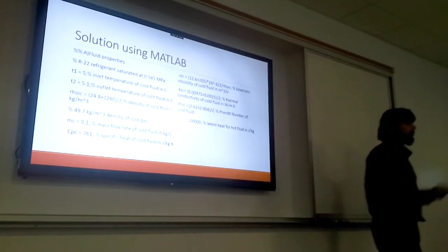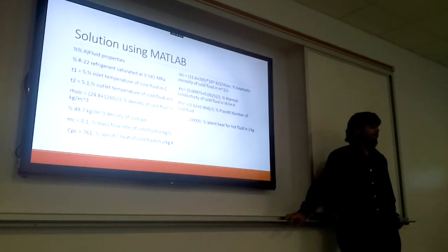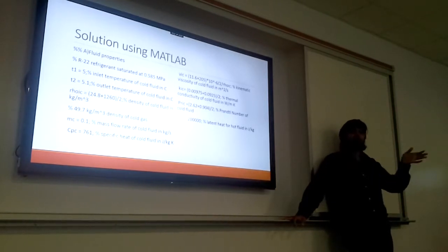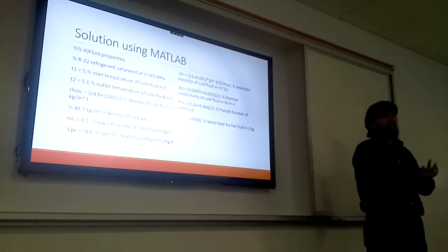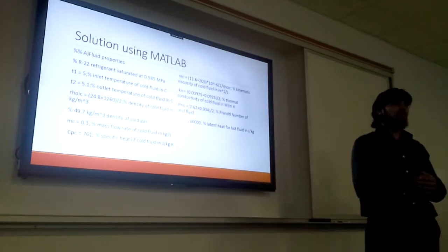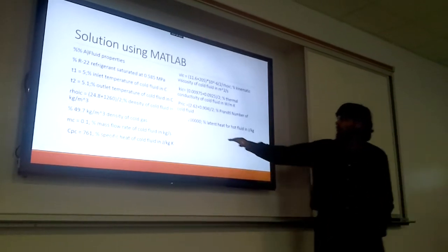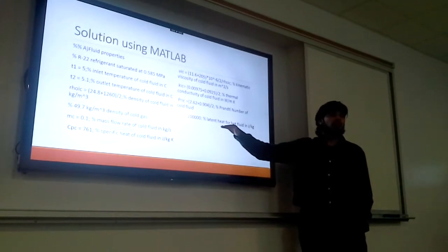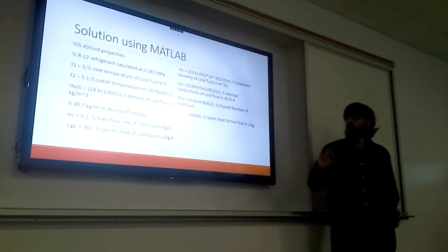Okay, and why do we, yes? So for each of the properties, we take the liquid and the vapor, and you can take the average. It's kind of like you did the average for the temperatures, right? Obviously you don't have a temperature difference here. What's the difference here? It's a liquid state and a vapor state. So again, it's not the best approximation. But nonetheless, it can give you a reasonable estimation so you can go forward with the calculation. But all of your heat transfer is coming from the vaporization. Basically, none is coming from the change in temperature. Okay, just remember that.